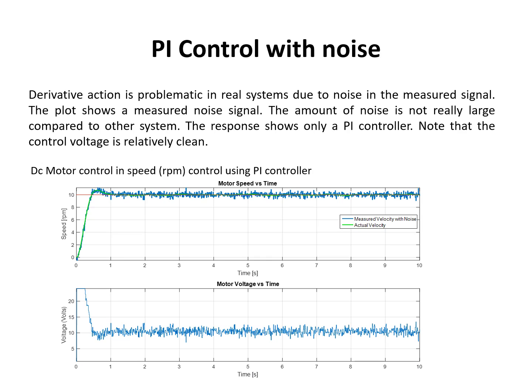Now remember that when we determine the derivative, we determine it using the last two error terms. So if we have a nice curve which looks like that, we will have our current error which is perhaps this point, and our previous error which is that point, and we can determine the gradient. And the next time we work out the error term is this, and again we will have a gradient which looks like that.